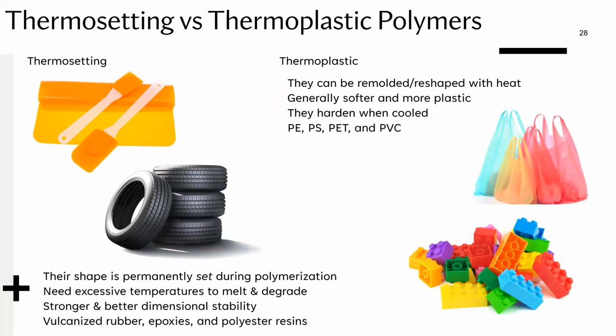and you have to heat them up to a temperature called the glass transition temperature, at which point they actually go from this brittle plasticky feel to sort of a molten plastic feel, or not really molten, but more of a gooey sort of look. And so you can then compress them, mold them into a new shape.